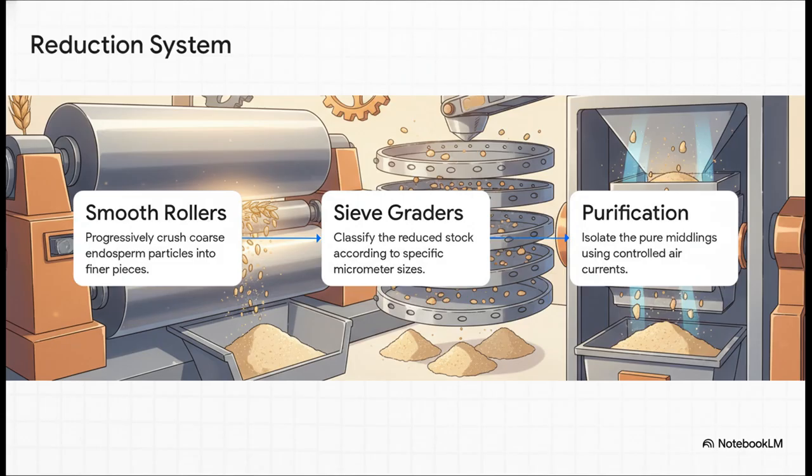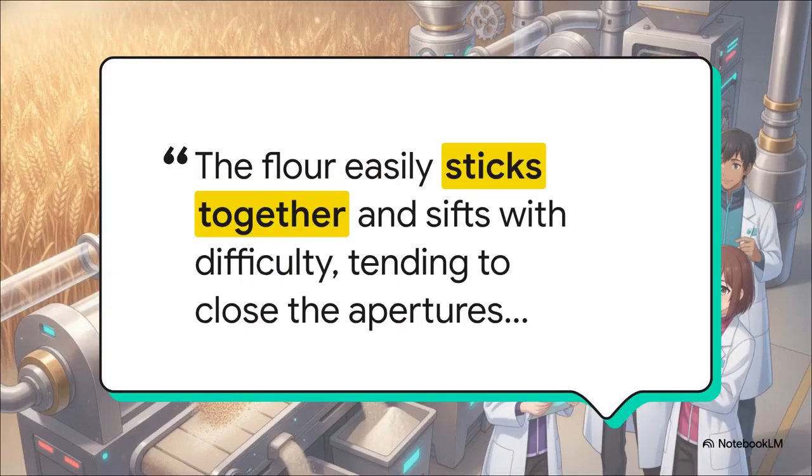Lowering this differential is critical for thermal dynamic management. If you maintained the high 2.5 to 1 brake differential with smooth rollers, the friction would generate extreme heat, actively degrading the starch granules and destroying your flour's functional baking characteristics. We have to be incredibly precise here.